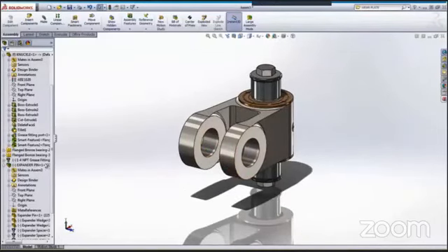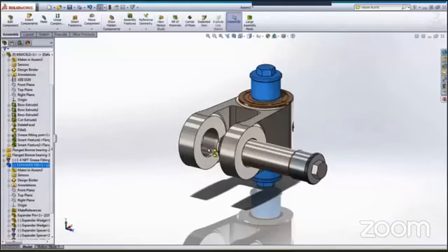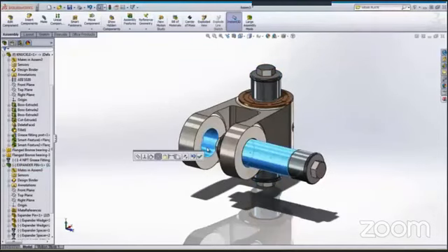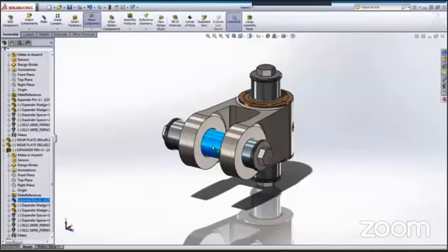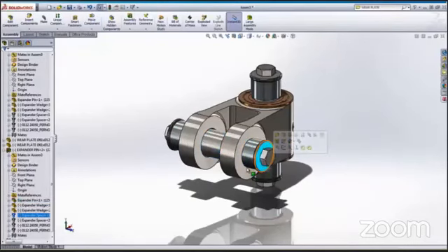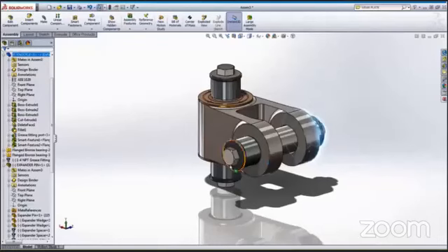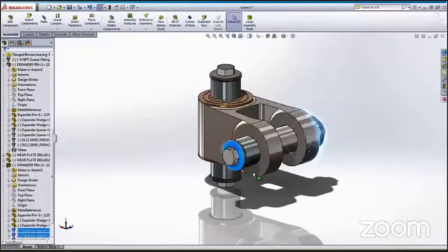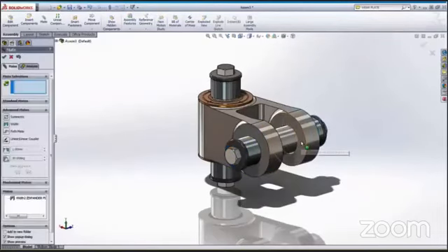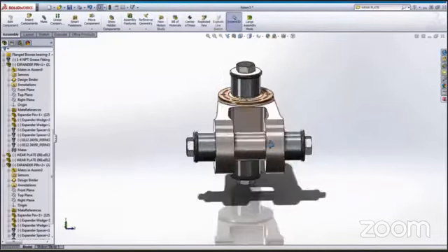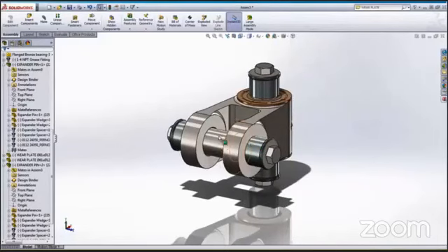The pin needs to be added to the hole on the left as well. So just drag and drop this one from the feature manager and snap it into position with a concentric mate. Using the mate again, we complete this one in no time at all. But this stage is too long for this application, so we will leverage the configuration of the pin assembly and use the 150mm version.